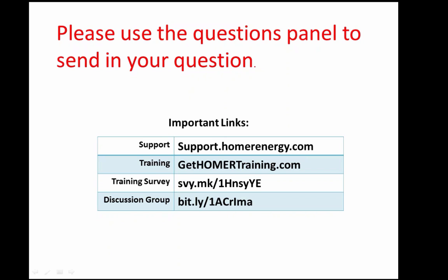If you're designing a system without a generator, sometimes it's pretty hard to avoid some unmet load, which is why we have a parameter, maximum allowable capacity shortage, on the project page to allow a little bit of unmet load, which is hard to avoid in a system without a generator. That's too specific a question to answer without seeing the file, actually.